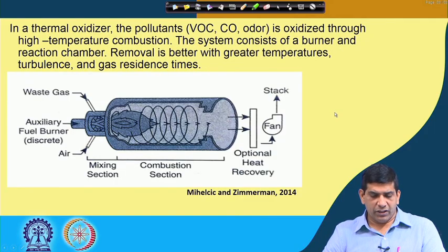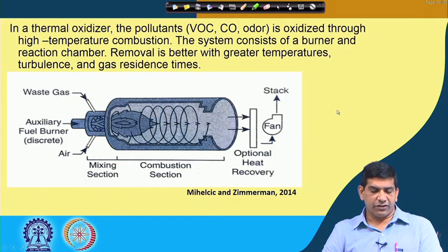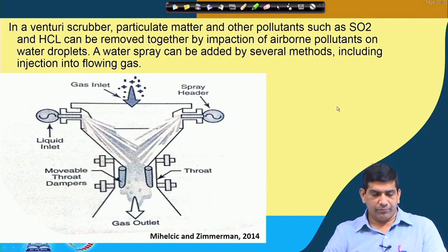Thermal oxidizer, where VOC is oxidized through high temperature combustion. The system consists of a burner and a reaction chamber. Removal is better with greater temperature, turbulence, and gas residence time. So, essentially you are burning all these organics and making the air cleaner.